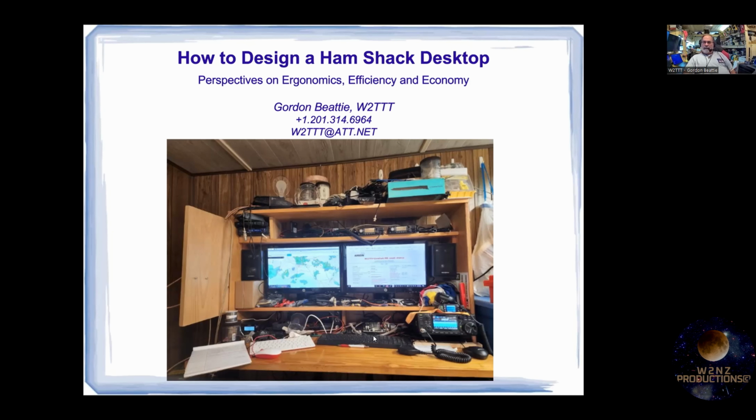It's a good question. Sudeepta from Kolkata, VU2UT, has a question. Do you have any lightning arrestor system? What distance do you maintain between the lightning arrestor ground and the nearest RF ground? Okay, so that's a real good question. In the ham shack where I'm sitting now, the lightning arrestor ground is also the earth ground for power and for any RF. Everything is grounded here. It's called a ring ground.